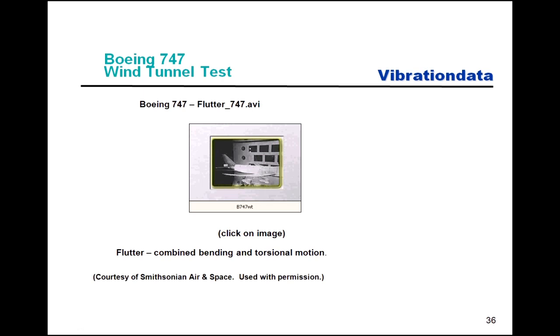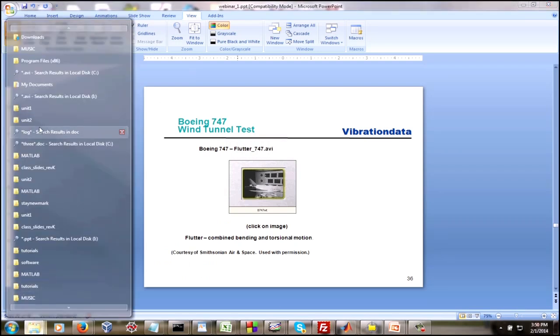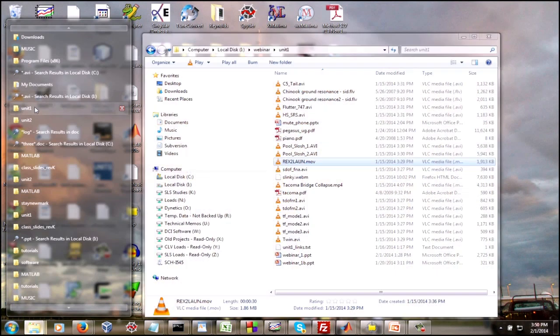But the classic one that's the most concern for airfoils is if the bending mode and the torsional or twisting mode coincide. And depending on the mass and stiffness distribution of the airfoil and other things like the turbulent boundary layers and Reynolds numbers and Strouhal numbers and all that, there are certain cases where this flutter mode can get set up.